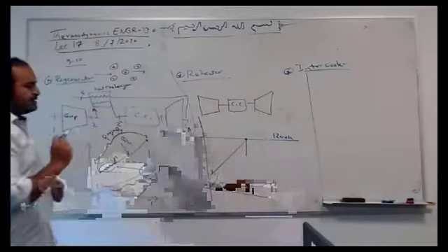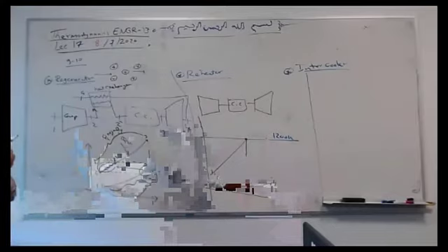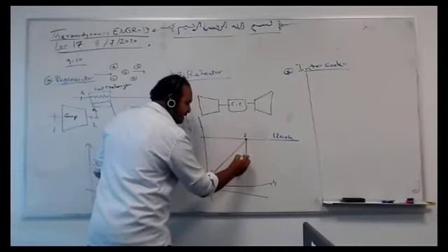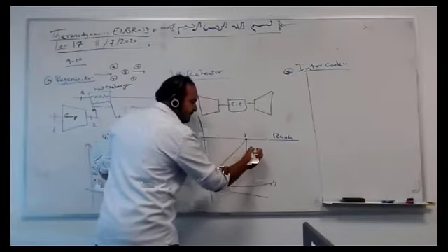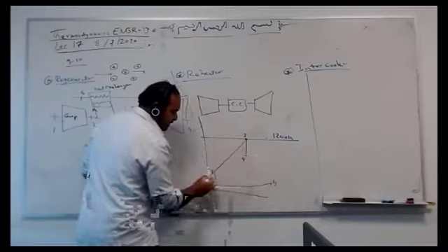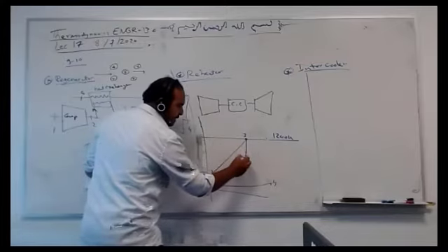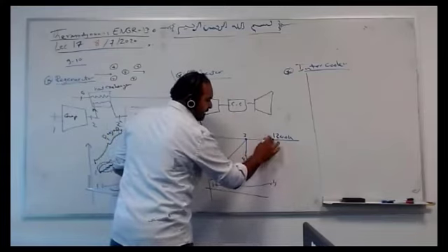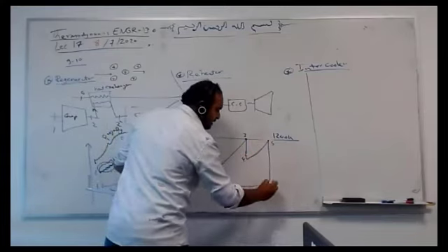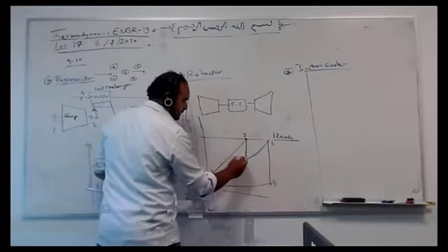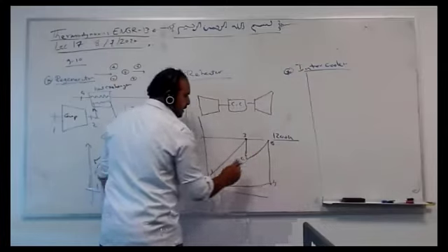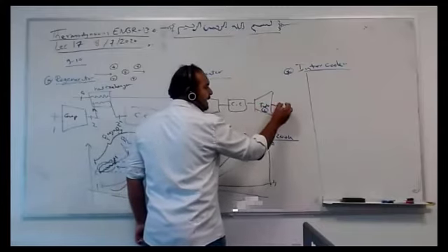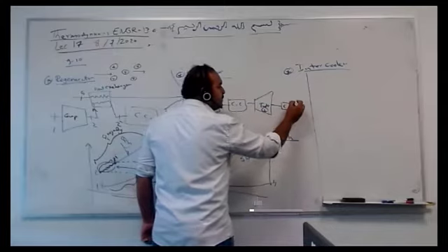Somebody smart said, okay, how about this? I'm going to do something very interesting. I'm going to come here, this is 3. I call this, for example, 4. Then I burn again. This is another constant pressure line. Then I burn again at a certain temperature, let's say T5, maybe less, maybe more. Then expand. So this is, let's say 5, sorry, 6, 4. So here I will add turbine 1, then add another combustion chamber, then turbine 2.